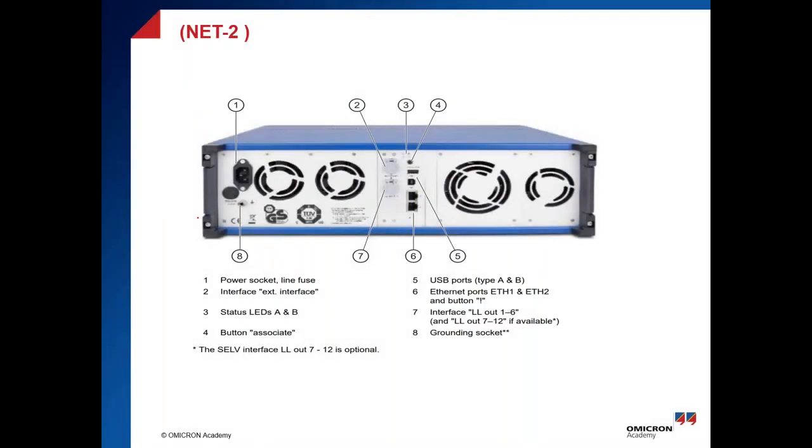Let's go to the back side, the rear side of the CMC, which is also very important to communicate with the CMC itself. I would like to give you some advice to avoid any hardware failure. The first one: please keep in mind that earthing is very important and mandatory for your safety and for the kit's safety as well. Please try to find a proper grounding before starting your testing. This is for your safety and for the device's safety.